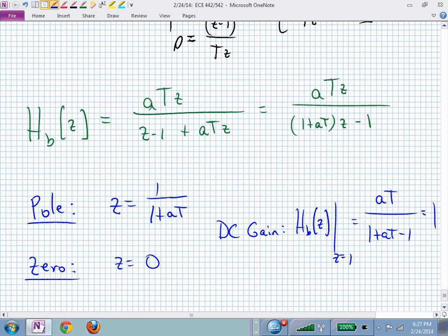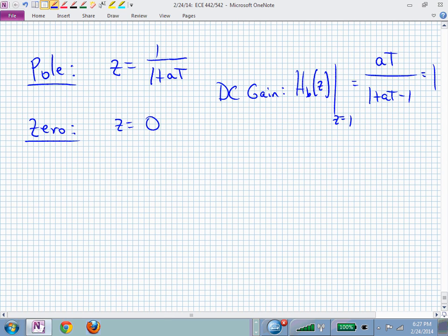We just are looking at different ways of finding discrete equivalents for, and in our example, it's just a first order. And we'll talk more about stability of these. We'll actually learn that the backward rule is better in terms of stability properties than the forward rule. If we start with a stable transfer function, we will get a stable h of z in the backward approach. We're not guaranteed of that in the forward approach.